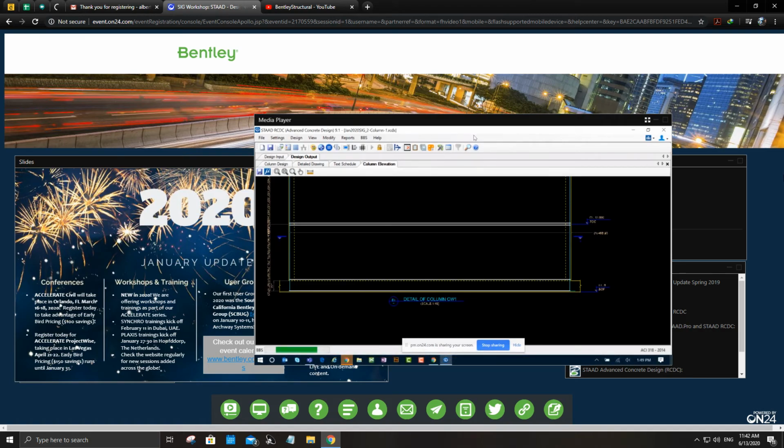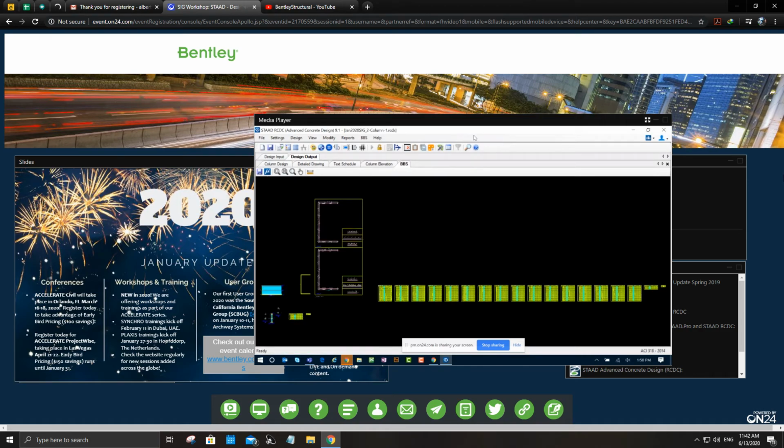Okay, so the way I'm going to answer that is that you are going to define your finite element mesh. Once you commit it to your input file using the parametric models, you're going to continue on and assign whatever properties to that finite element mesh that you normally would in STAAD.Pro, which includes affecting the direction of the local z-axis. So you can go to STAAD.Pro and highlight the walls you want to change.